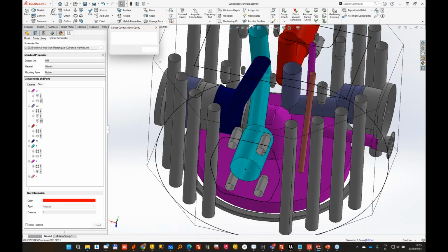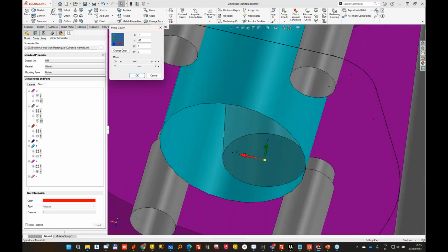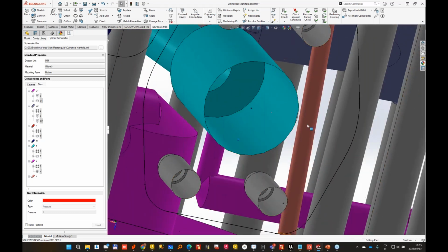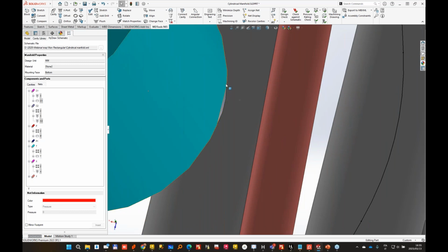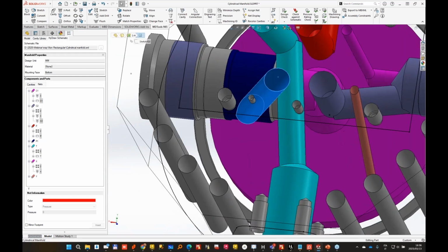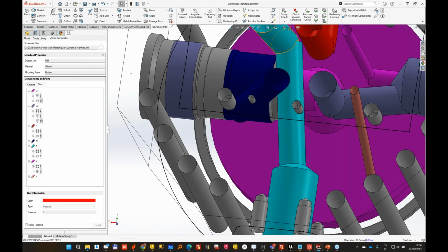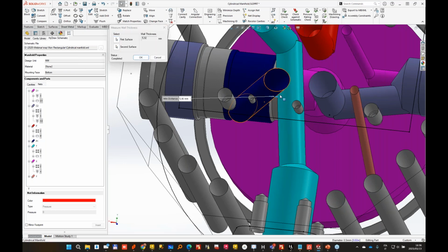So here we have two possibilities. One is possibly moving at maximum here. As you can see, it's touching, really going almost tangent to the original drill, so that will not be a problem. And this we can incline a bit more. Of course, we can do measure wall thickness. Now it's 6 millimeter, it's fine.